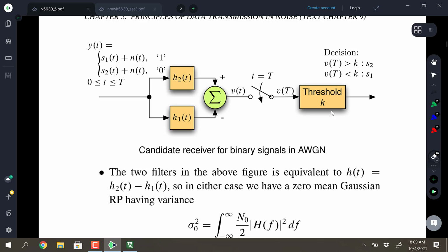And if you want something to think about, though this is not strictly required, you could think of S1 and S2 being orthogonal, in a signal sense. Then the filter H2 pulls out only the S2 signal, and meanwhile the output of filter H1 is nothing when S2 is being sent, because these filters have this orthogonality property. And the easiest modulation scheme to think of for that, I think, is frequency shift keying, where you think of two bandpass filters. Yeah, exactly, two bandpass filters. So that's kind of where that comes into play.